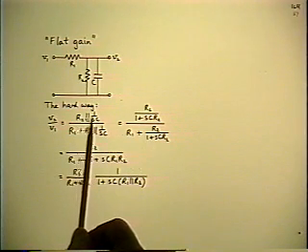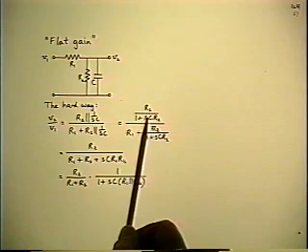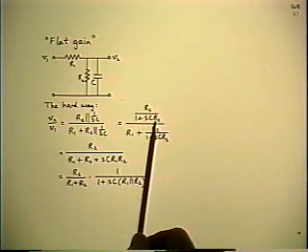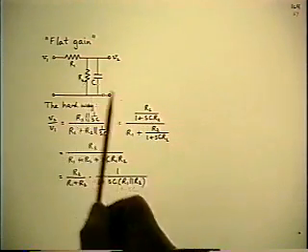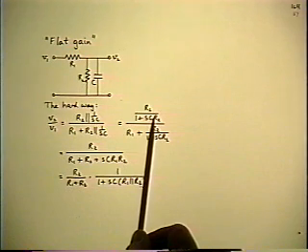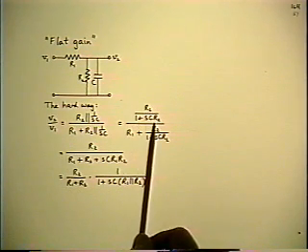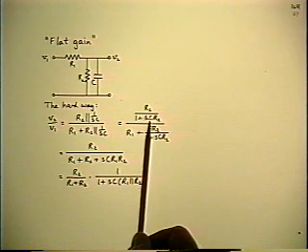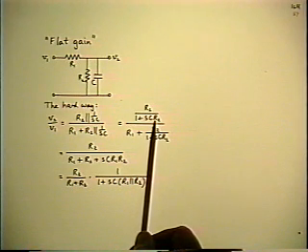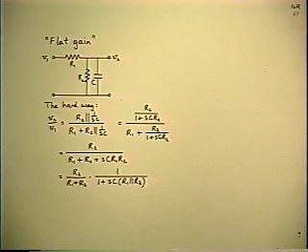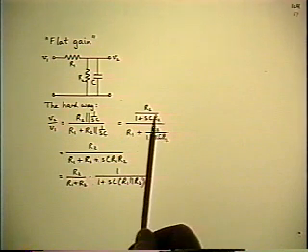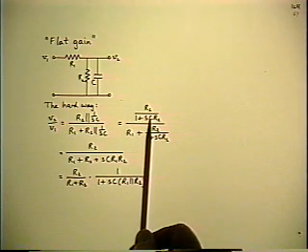Now, first you multiply out the parallel combination. And here's one simple result worth remembering. A parallel R and C has an impedance which is equal to the resistor by itself divided by a single pole. And the value of the pole is the RC time constant. One line of algebra is the only thing that's missing in writing that answer down.